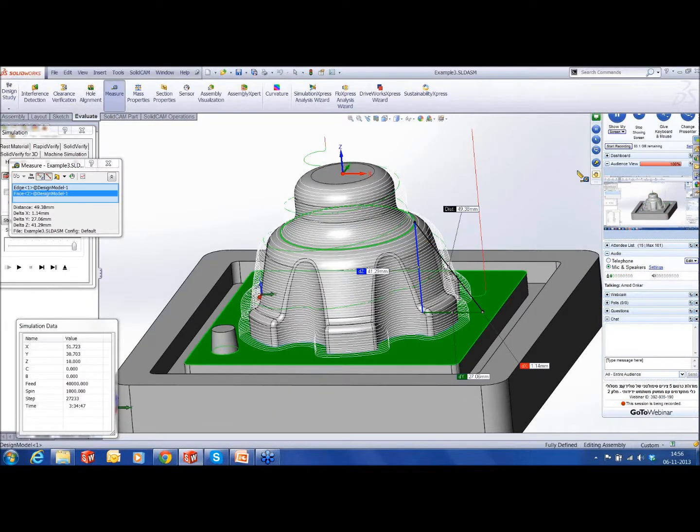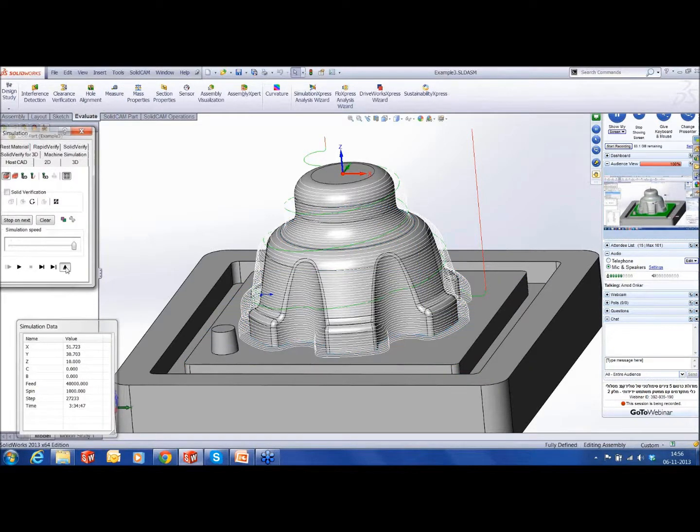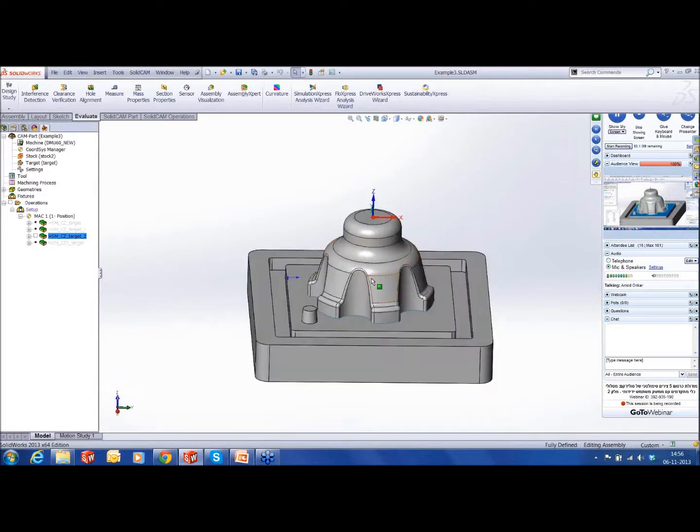A 41 millimeter tool, let's say about 6 diameter, would be an L by D ratio of more than 6. This again can cause vibrations. This again can cause chatter. So now I would like to convert this 3-axis toolpath into 5-axis. By doing that, I can use shorter tools and approach these deep areas like what we saw there.